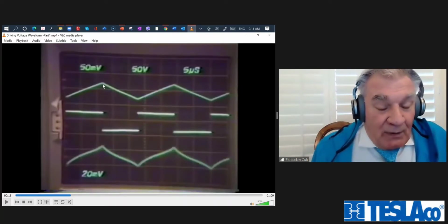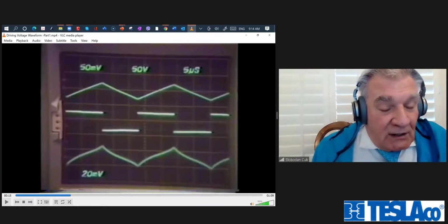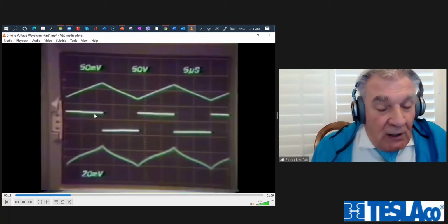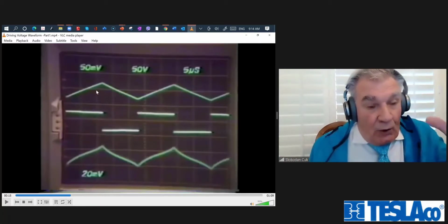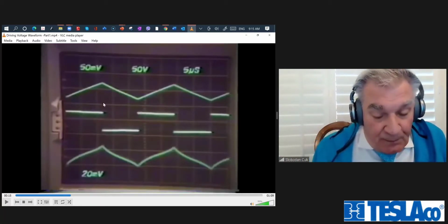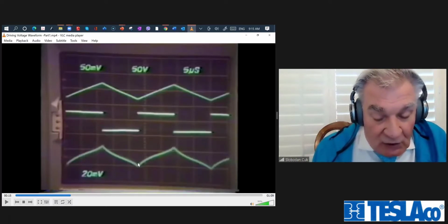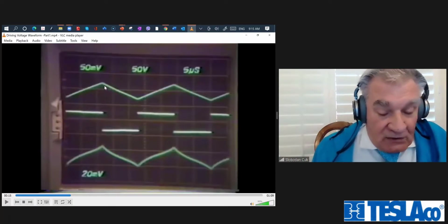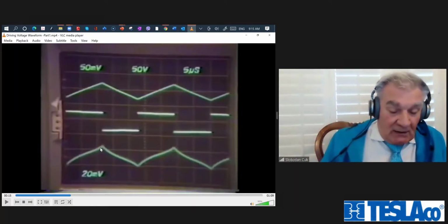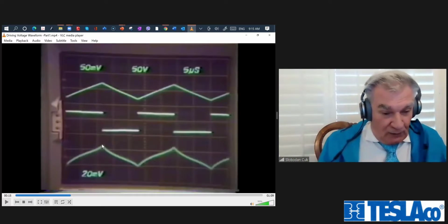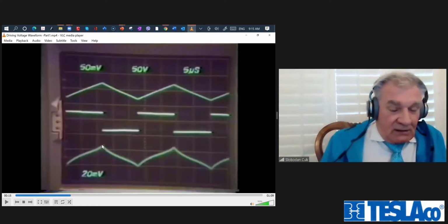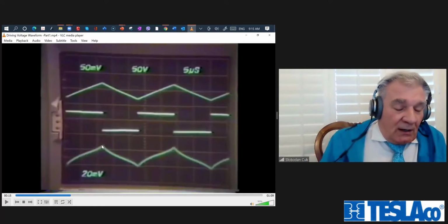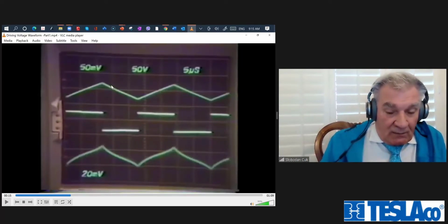But because the core has its nonlinear characteristic, the more I drive the core toward the edge of saturation, the smaller the slope and the more current it will draw. So this spiky effect here shows that the actual current will be distorted and the flux is never distorted, right? It really reflects that at this point, I'm going into the magnetic characteristics of the core, which is no longer in the linear region of the magnetic material. It's starting to go into saturation, and the more I drive it, the more I get there.